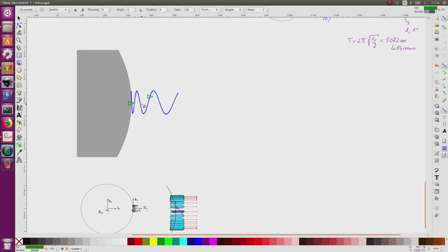Now what happened in practice is that the robot is actually here, and the inertial unit thinks that it is here because it is consistent for the inertial unit since it has been badly initialized. Now this corresponds to a nonlinear effect.